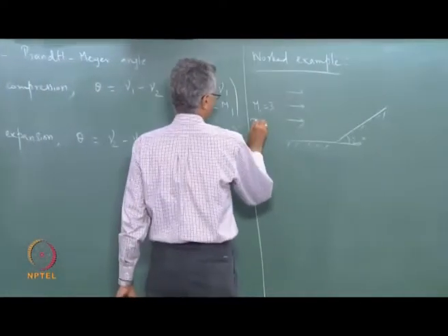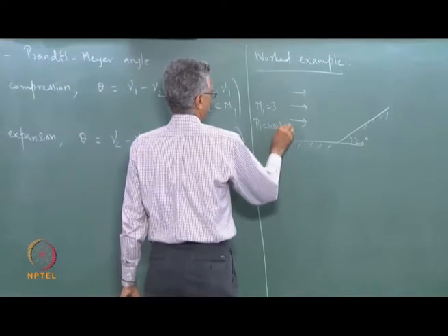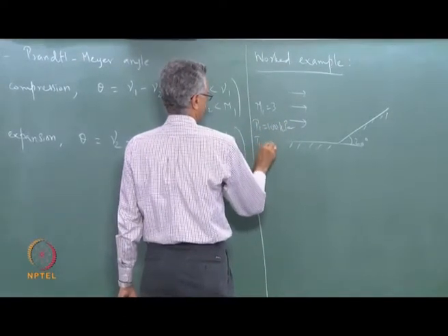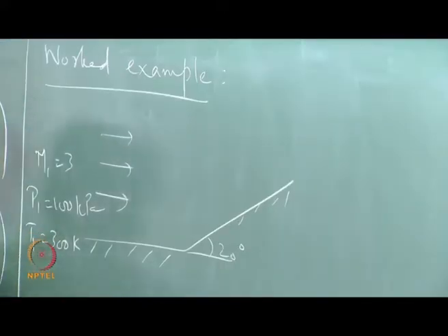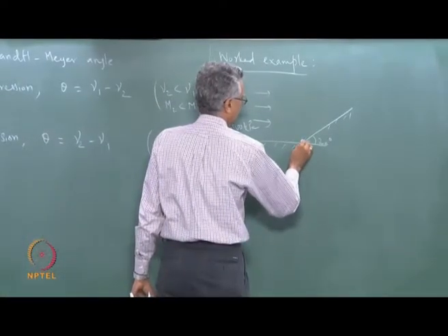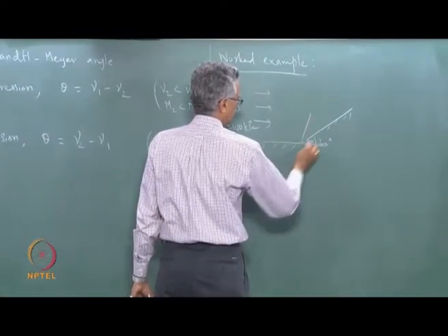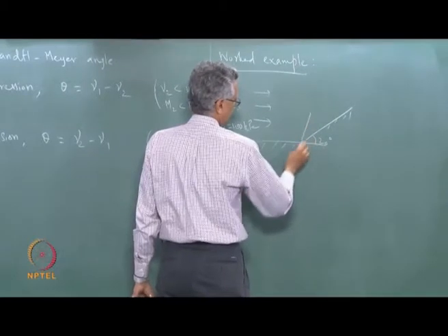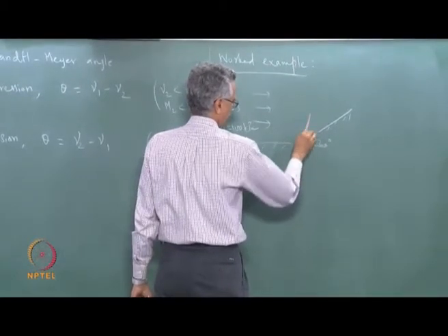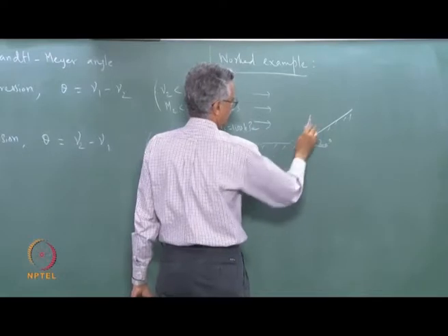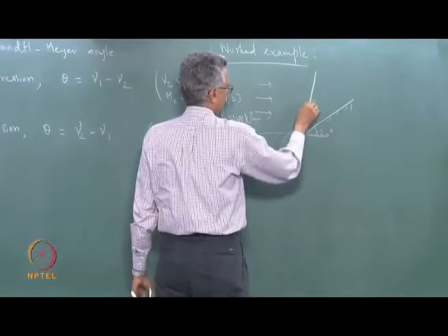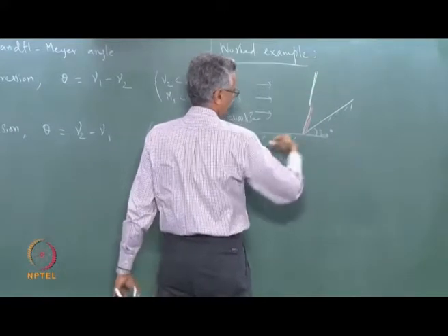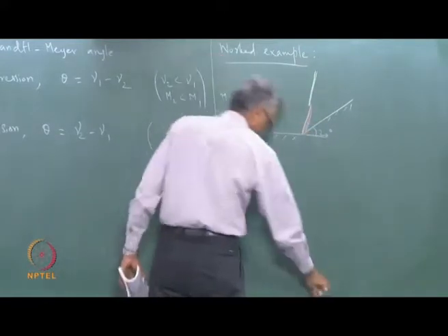P1, the static pressure, is given to be 100 kPa and the static temperature is 300 K. So the flow encounters a compression corner like this, and as we discussed in our previous class, we have a series of expansion fans, right? A set of expansion fans is generated from here, and this then coalesces into a normal shock. As you make it smaller and smaller, the fans coalesce.